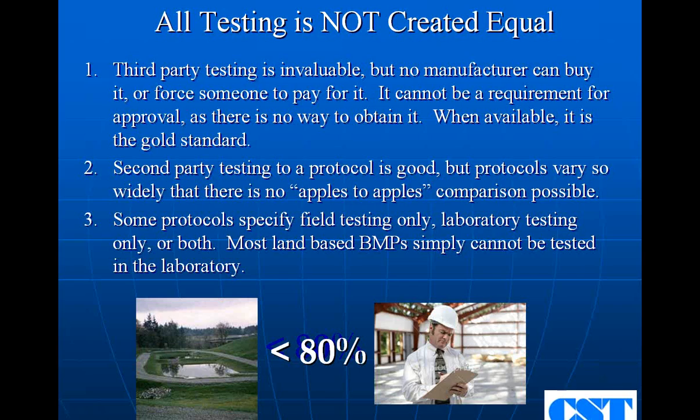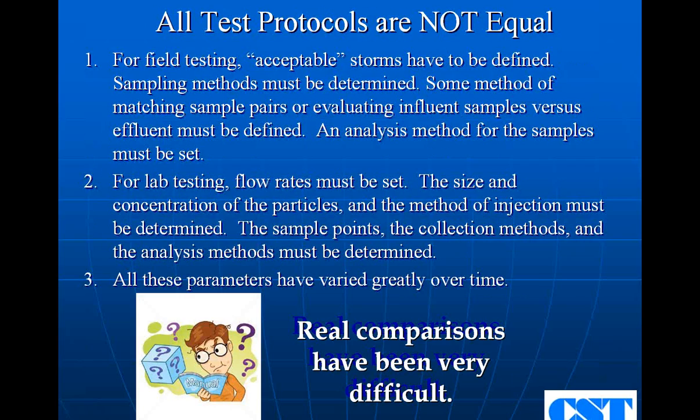You could say, hey, I passed or I failed, but you learn from those field studies. Those land-based BMP studies that were done in Charlotte are among the very few where there's good QA/QC testing done on field-based. And some things like a sand filter are just so difficult to match influent to effluent. You really have to look at composites and some other things.